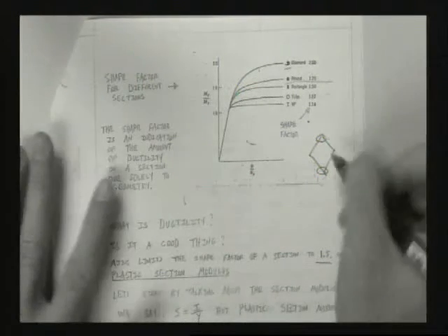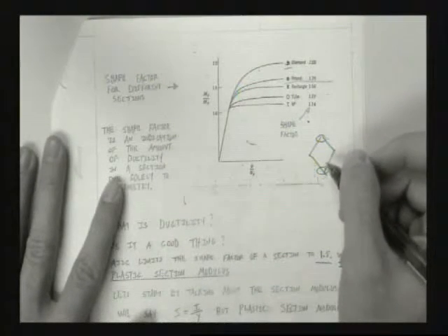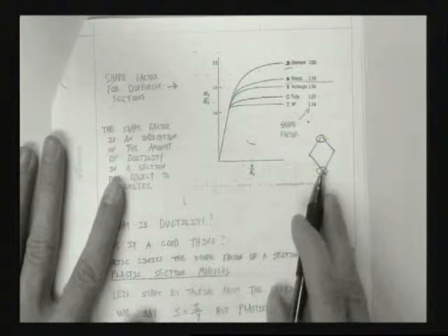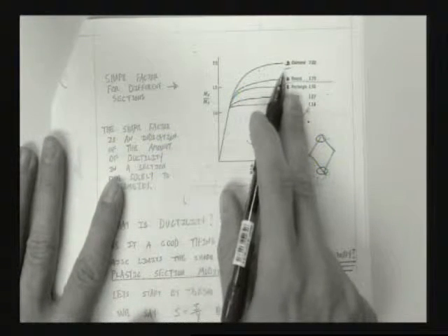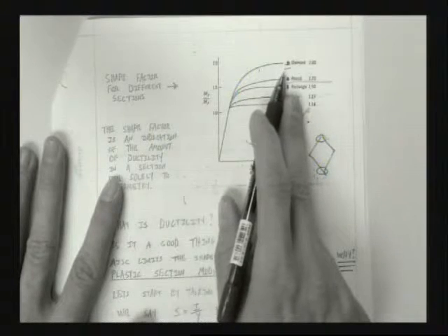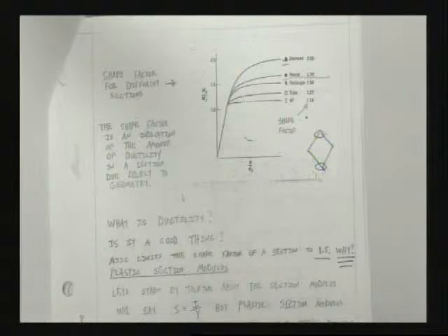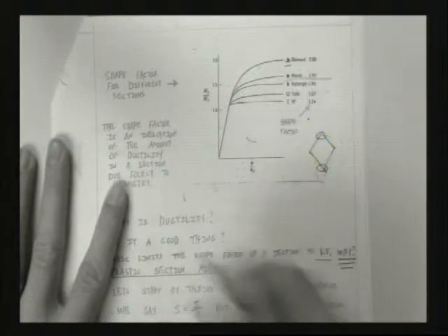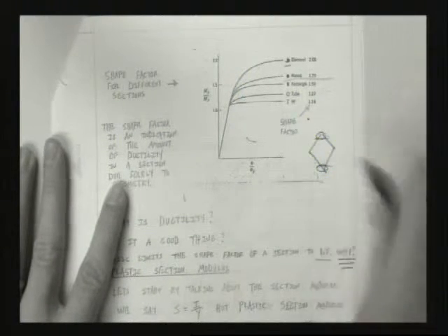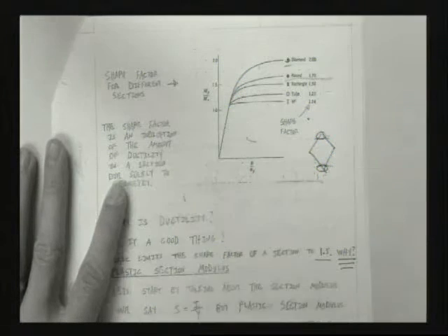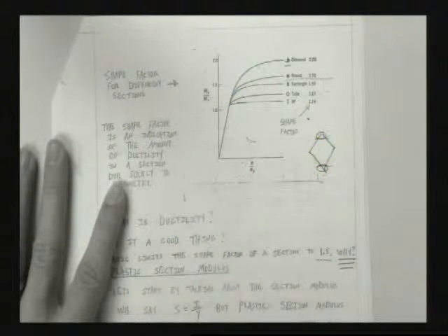So if, as you're loading, you start losing stiffness, then you would have a structure that would have plenty of ductility, a bend but don't break type attitude, but it would be very flexible. It would move a lot when it's loaded. You would start yielding it pretty early and say, oh, don't worry, it's not going to fail, but it may become springy, more flexible, more bouncy.